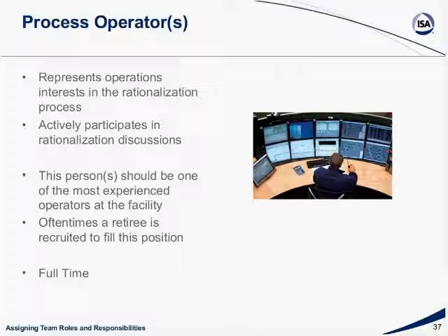The information that's recorded during the rationalization process serves as a great training platform for the operators going forward, for the new operators, the ones that haven't seen these things come up over and over before, whereas an experienced operator knows what they're doing right off the bat when something happens. The new operators will need guidance, and it's the information that's generated through the rationalization process that gives them that guidance. So this is really very, very key. You need to have a senior operator and/or operators, and they need to be full-time participants in the rationalization process.